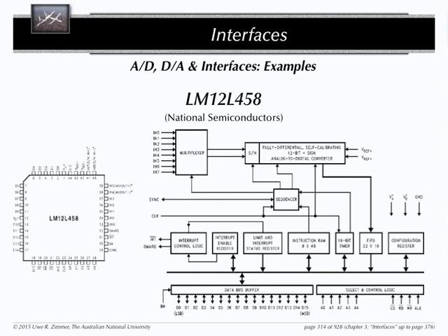And it will exactly operate like you expect it now. You read from this FIFO system, from this address, and while reading, you will also delete it from the device, just by reading it. You will read it from the device, it will be eliminated, it will be switched to the next entry in the FIFO, without you doing anything else on the device.